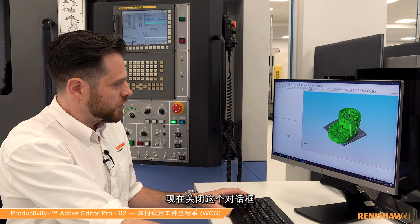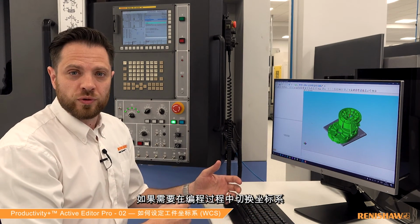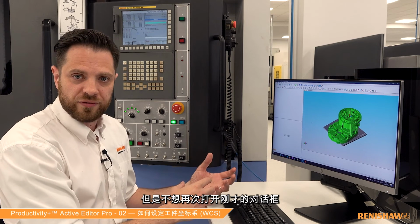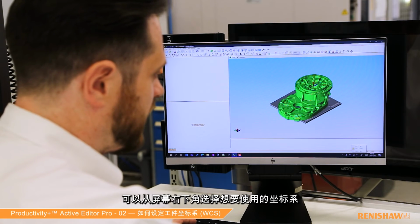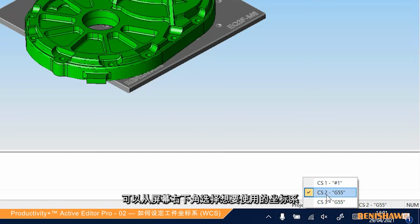So if I close this dialog, if I do want to switch coordinate system in the middle of programming and I don't want to have to open that dialog up again, we can actually go down to this bottom right-hand corner here and choose the coordinate system that we want to work in.